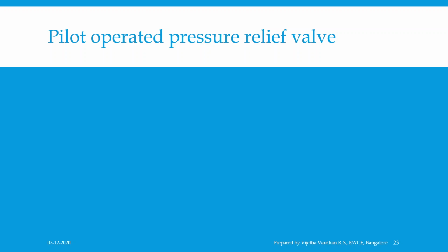direct acting pressure relief valves, which are also called spring loaded poppet relief valves, are generally used for low flow or low discharge applications. They have internal leakage below the cracking pressure and respond rapidly to variation of system pressure, thus making them ideal for relieving shock pressures.